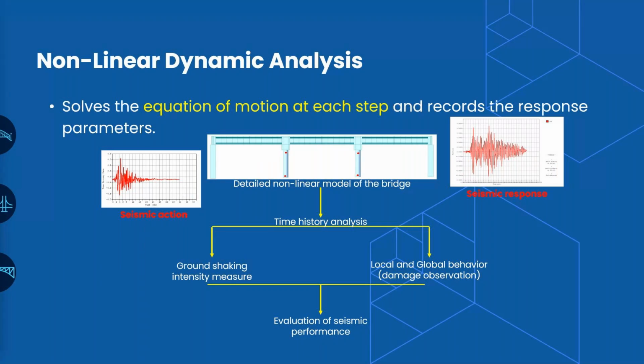Before starting with the nonlinear time history analysis, the question is, why do we require the nonlinear time history analysis even if we are having a detailed analysis such as a pushover analysis? The reason is that the pushover analysis is one of the approximate ways to compute the nonlinear behavior of a structure. As the system is dynamic in nature, we have represented it in terms of a static system in the case of a pushover analysis to assess its performance approximately.